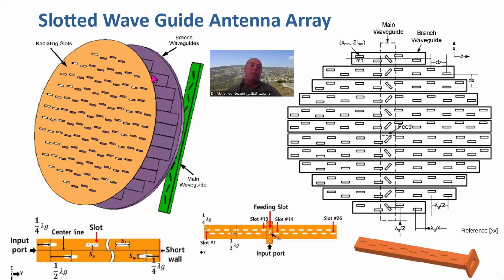So we've got a bunch of waveguides that are carved in metal, and then we've got a lid on top of them, which is basically the slots. And you can see the slots. And this comes down as a cover for this. And the feed is basically every one of these waveguides has a slotted hole inclined in the back, and this feeds in the back. And you end up with a slotted array pattern like this, okay?